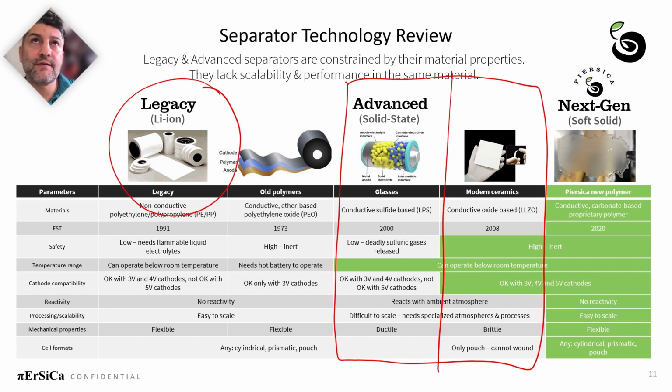And you've got to keep in mind about 30% of the volume of a cell, of a lithium-ion cell, consists of electrolyte. So if you make this type of conversion from legacy to these type of materials, all of a sudden 30% of your cell is 3 to 5 times heavier than before, it's very challenging to obtain high energy density in these batteries. This is something that is not talked about so much, but it's a huge impediment to obtaining high energy density.